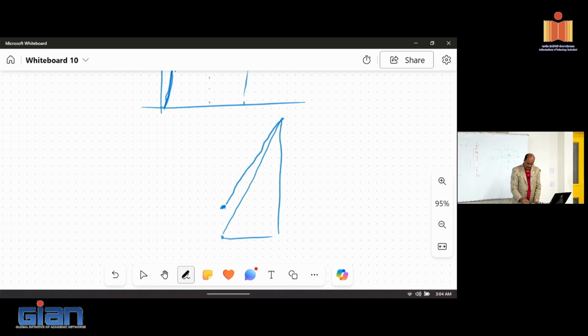Because your plastic moment capacity is not this, I mean, this is a plastic moment capacity, but it's been shifted here. This is where the plastification takes place. So as a result, you can see your slope goes up. So the column is going to see larger shear demand now than what you assume for a cast in place situation. Right? So your shear demand has gone up.